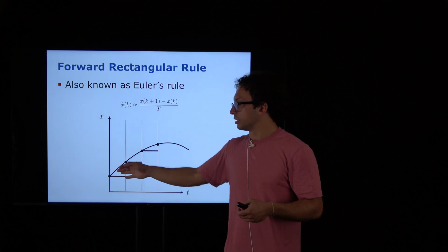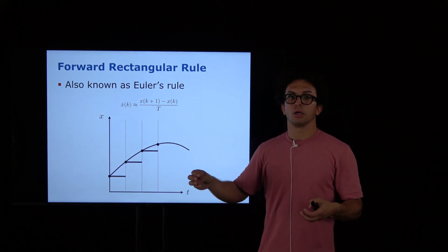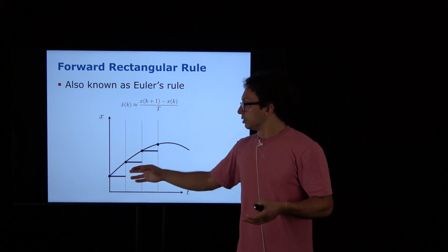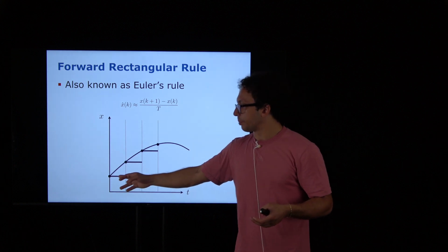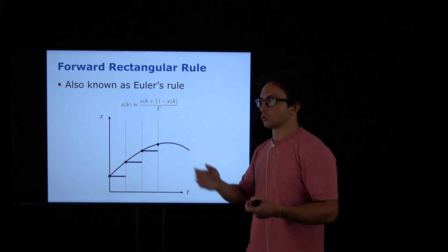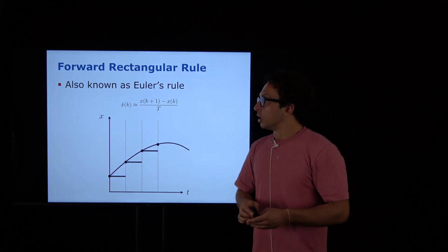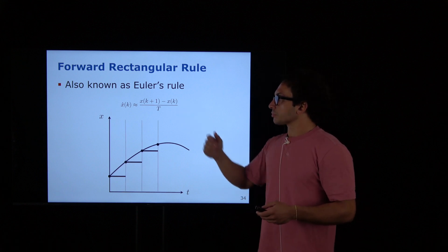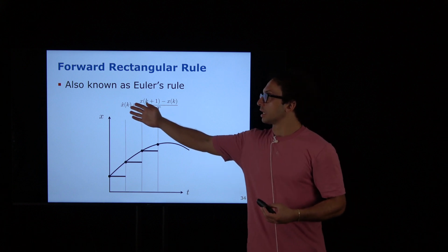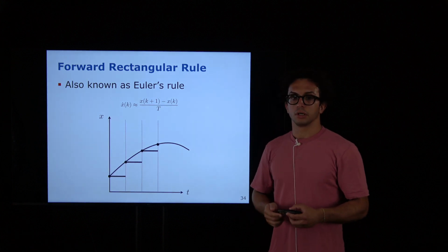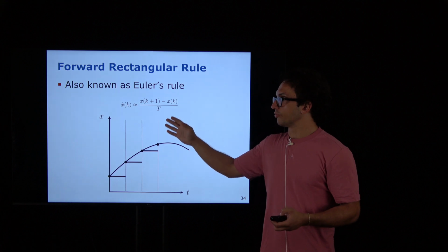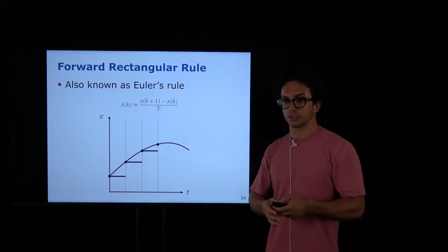Of course, when the sampling time is very, very small, this maybe can be accurate. If the sampling time is quite big, you can understand that this is not approximating this curve very well. So this can introduce problems. This is how the time derivative in continuous time is approximated for discrete time. And basically this is the Euler's rule for going from continuous to discrete.